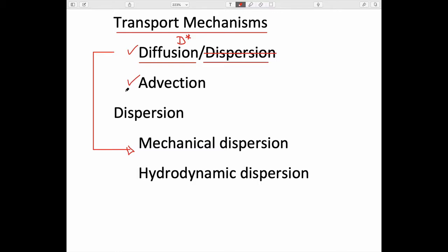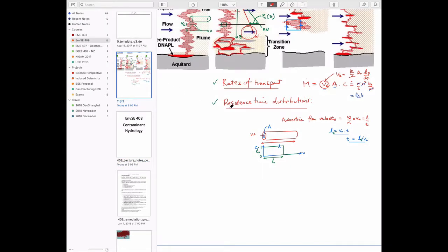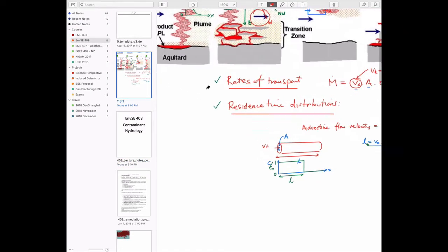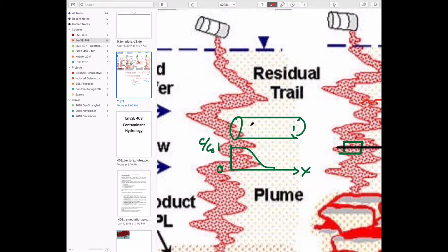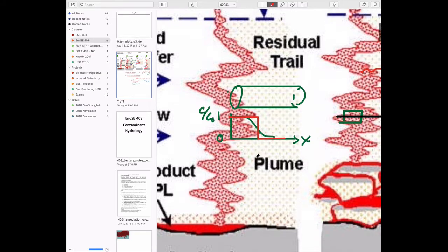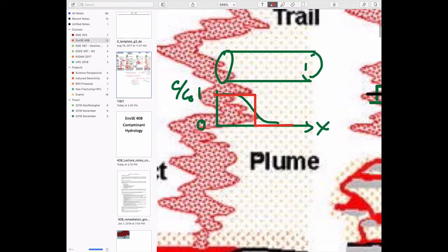The other mechanism that we can accommodate in a more sophisticated way than looking just at this behavior that we alluded to here is that if we go downstream, everything that you said so far would say that we'd expect the plume to look like this, a step front for plug flow. We drew it in this as this green part where we have diffusion acting.